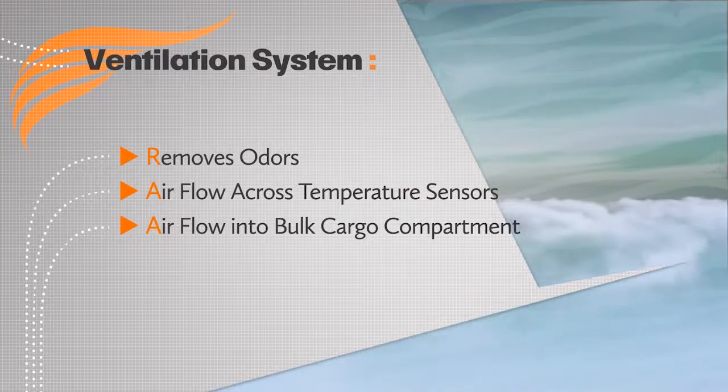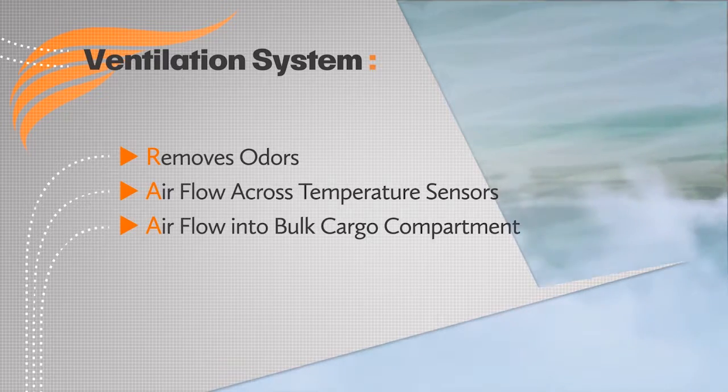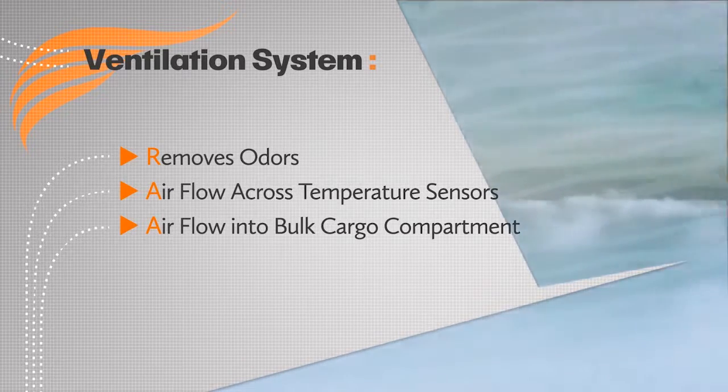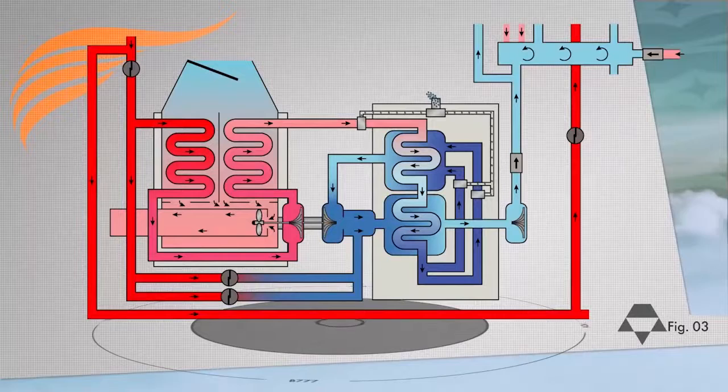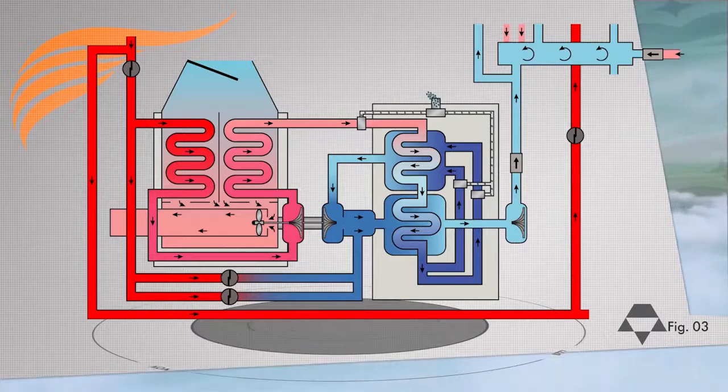We've mentioned the word pack a lot during this lesson, and it's now time to have a specific look at what packs are and how they operate. The word pack, as we mentioned earlier, stands for Pressurization and Air Conditioning Kit. The 777 has 2 identical packs that essentially provide the housing for all the cleaning, filtering, and cooling of the ram air that is conditioned to enter the cabin.